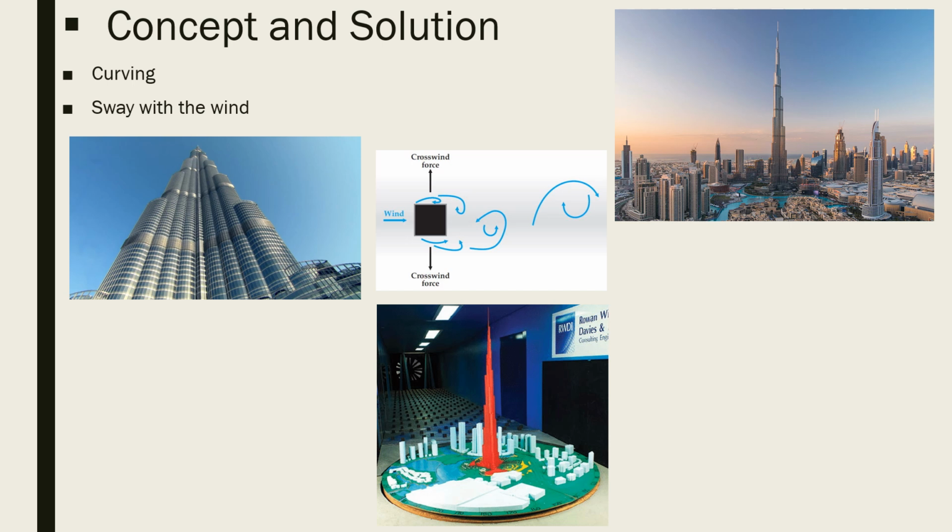So with this enough data, engineers come up with a solution to reduce the wind load: curve the pattern. It improved the outer buttress, and obviously there are many ways that they can curve the building. So they use the most effective one, which is a round shape, and with enough round shape, the building becomes curved and slender, which prevails over the wind load.